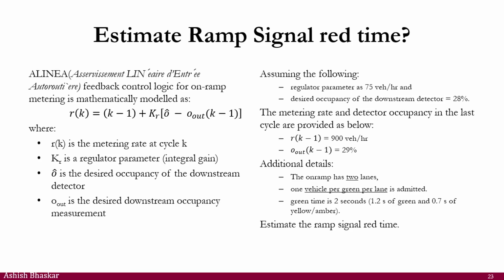And if you're letting two, you have to increase your cycle time to twice that, right? So if it was 4 point something, you have to make it 8 point something. Then after every 8 seconds or whatever, 8.36 seconds, you're letting two vehicles enter. So on average, it is 4 seconds per vehicle you are trying to enter. Does it make sense?